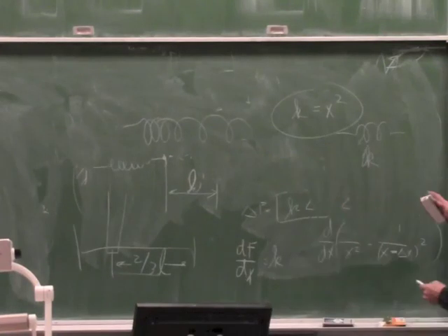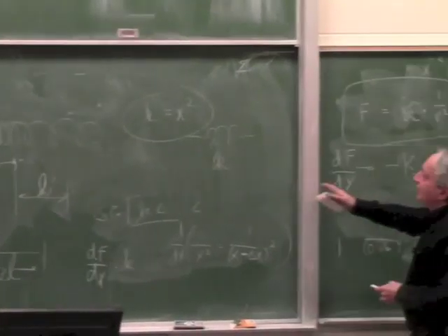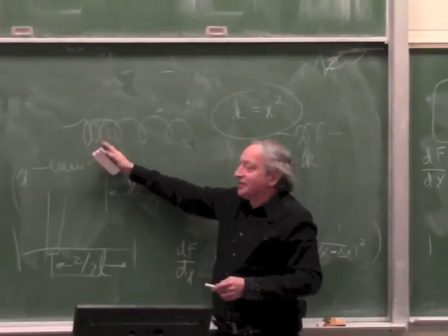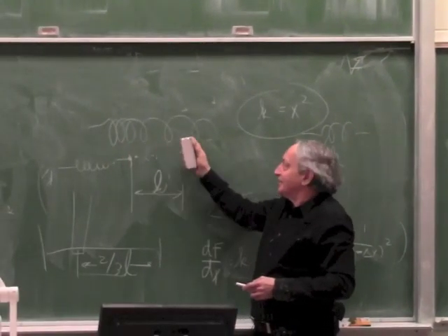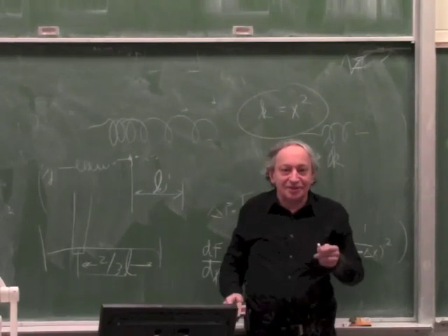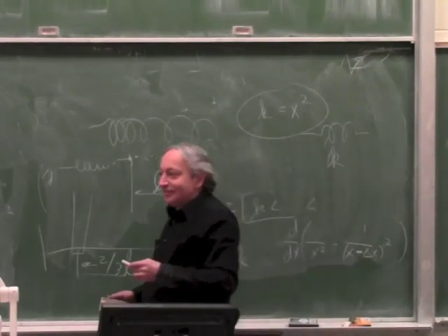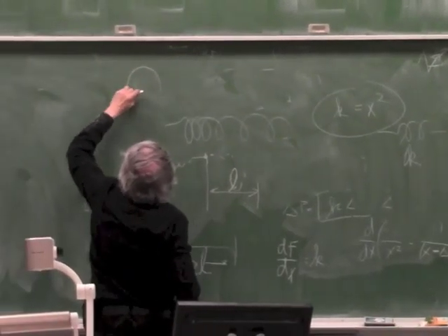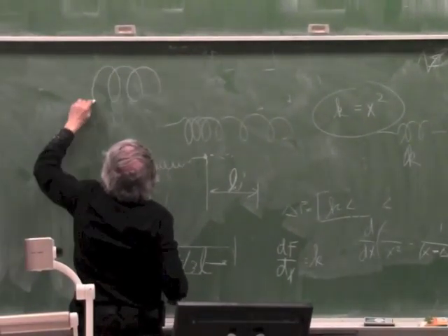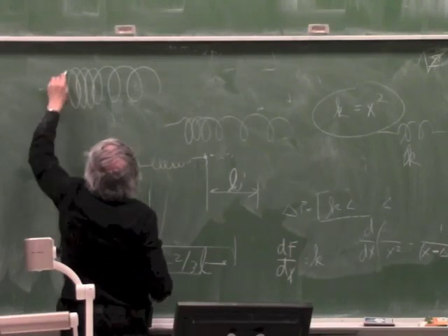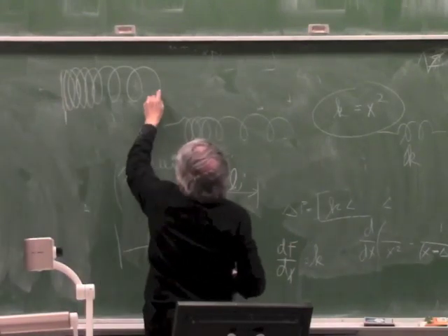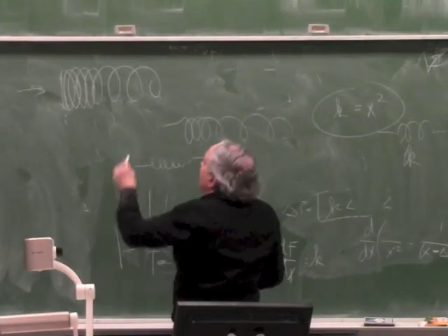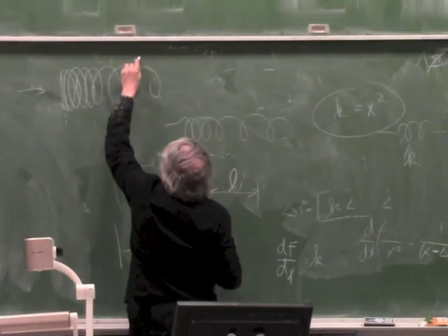You vary the pitch of the helix, but you make it a compression spring. So these turns start touching, and then there are fewer and fewer free turns, so the k goes up. If you make a compression spring, not a tension spring, where the pitch of the helix changes, and you push it in compression, every turn shrinks.